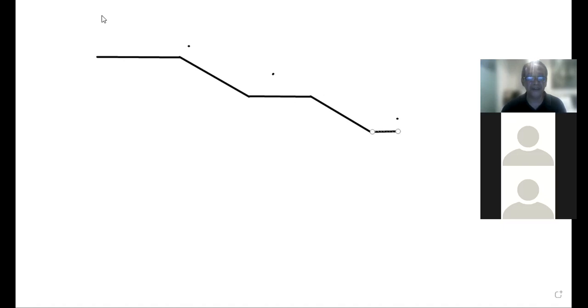Cuma we have to be aware di mana penyokong support for the staircase. If the staircase support dia ada one support over here and another support di sini, then if only 2 support yang ditunjukkan, only 2 supports, then this would be our span from somewhere center of this support sehinggalah pada center of this support. Right hand support to left hand support, and this would be our overall span L. And this can be represented sebagai, okay, as a beam.